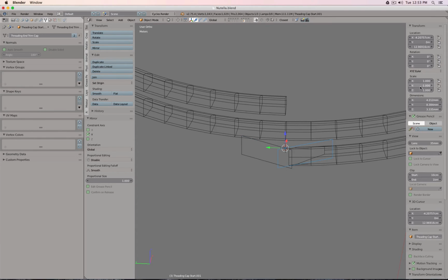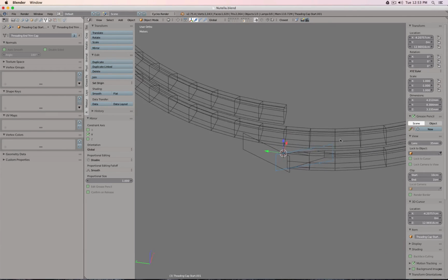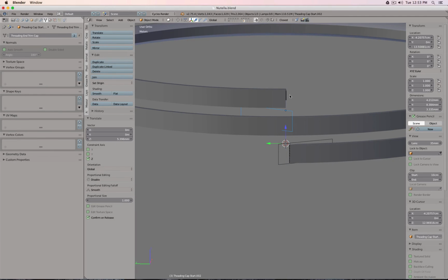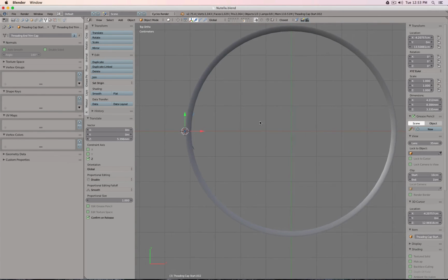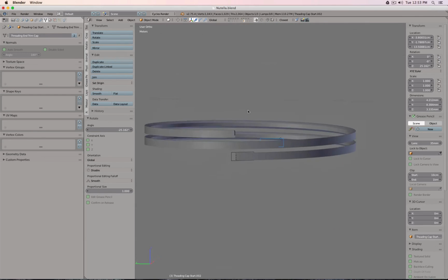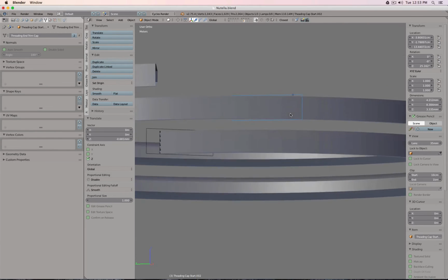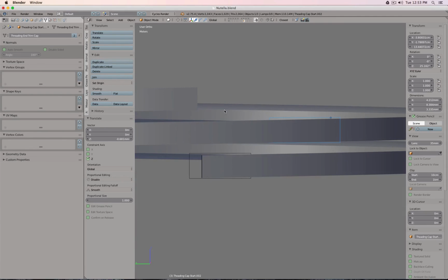And the way how I did it is actually, as you can see, it worked with the scale. So the flipping, actually the mirroring, inverted the scale a little bit. Okay, because now I can bring this one up to where I need it. Shift Z, cursor to center, switch back to the pivot point, R, rotate it over. Let's adjust this correctly. Okay.